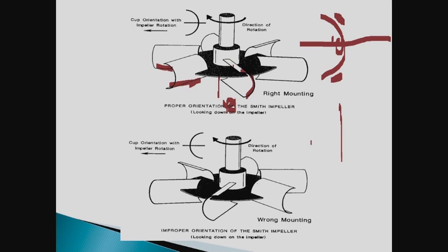Okay, with a flat blade, like the disc style, the gas cavity fills in. As a result, the dispersion goes down significantly, and this impeller gets flooded.